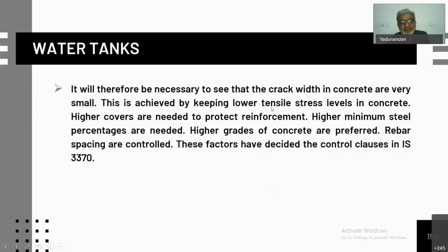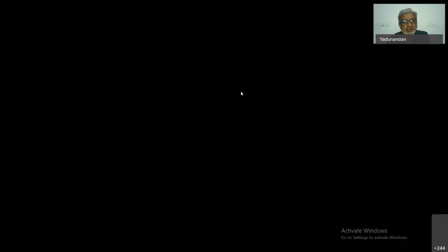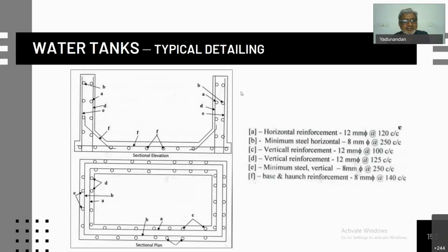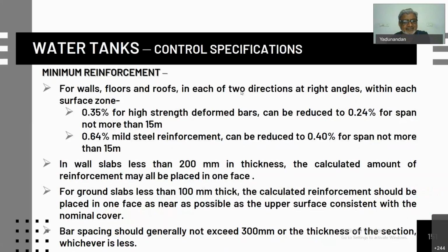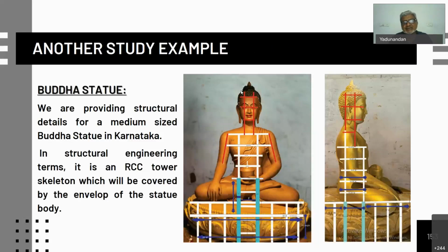consider these. These days chemicals have come with very high capabilities. You have to use those chemicals and provide waterproofing and protection of reinforcement, and design the columns for regular working stress loads, and design the walls and components of the water tanks for that condition so that the performance is guaranteed. Because it is in constant contact with water, minimum reinforcement percentages, number of face reinforcements provided, and spacing of reinforcements are more stringent than for ordinary structures.